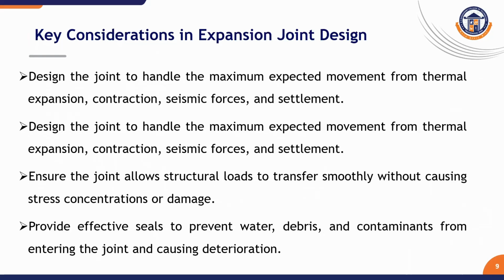entering. So in expansion joints, we design the joints to handle the maximum expected movement from thermal expansion, contraction, seismic force, and settlements. Similarly, it provides effective seals to prevent water, debris, and contaminants from entering the joints and causing deterioration. These are some of the key considerations in expansion joint design.